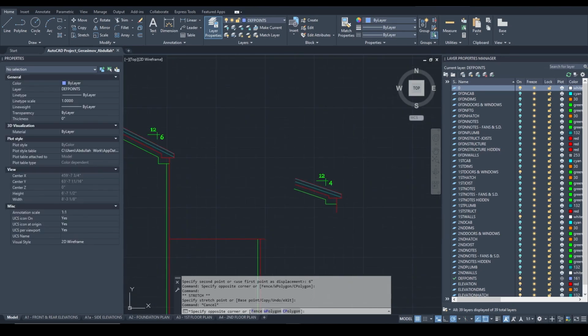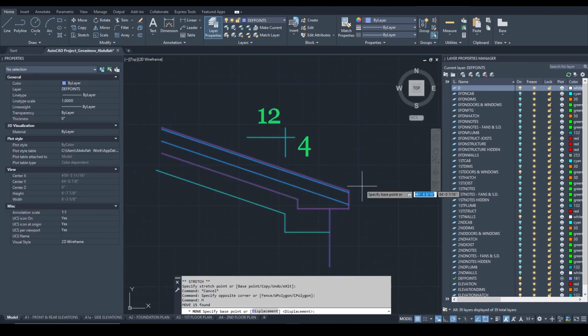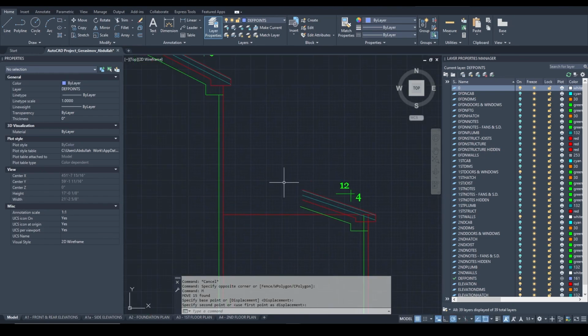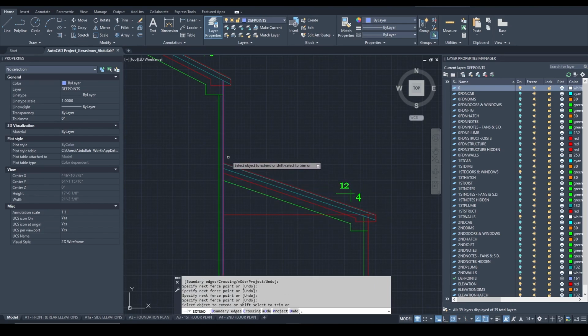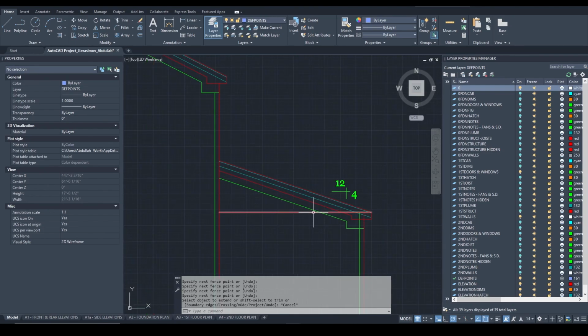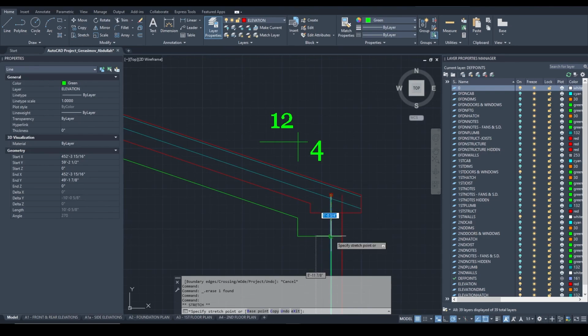extending the green line, copying the entire assembly, and moving it from the right corner to the overhang, and trimming the excess. Now in this case, we're going to have all the lines extend up to the left red line, and I pressed EX for extend. Let's trim the pieces that we're not going to need.